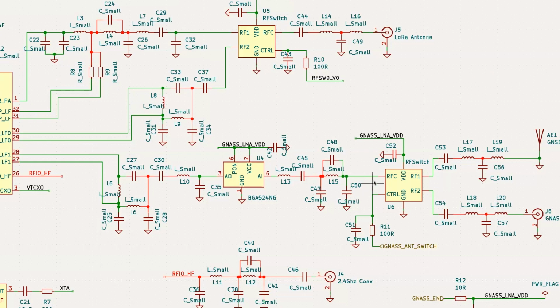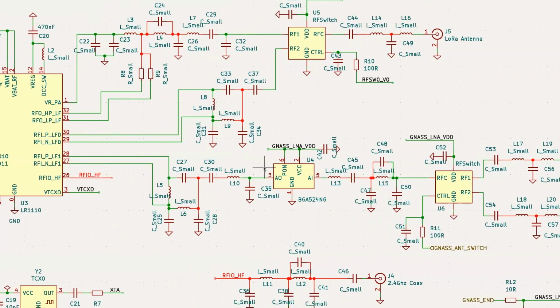On the PCB, are we talking about using a UFL, or what type of antenna breakout do we want? Yeah, UFL. I don't have one right here, but we could use a tiny little dongle or a little tail on UFL to break out to whatever format you want. Yeah, I think that's best. He mentioned the board is kind of dense, and we're going to have to use a UFL. Yeah, I agree. Cool.